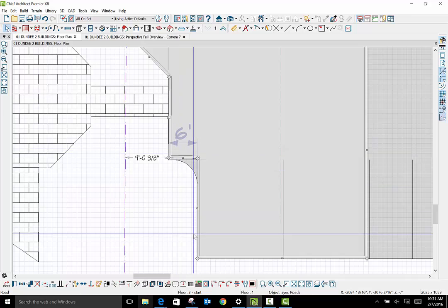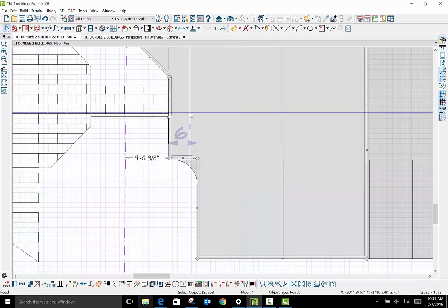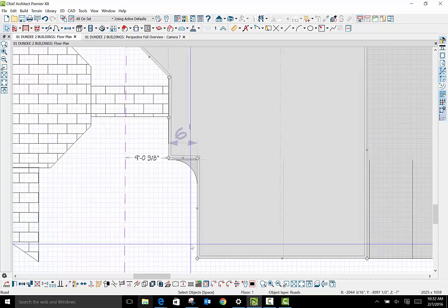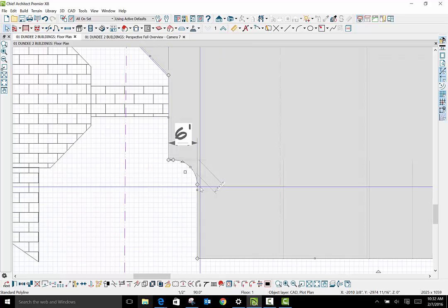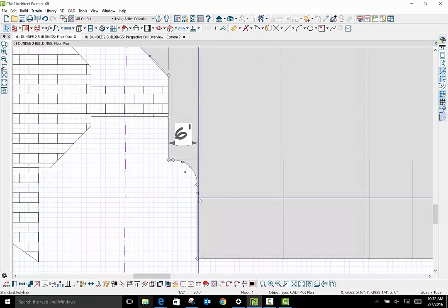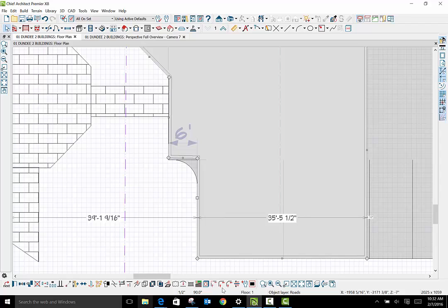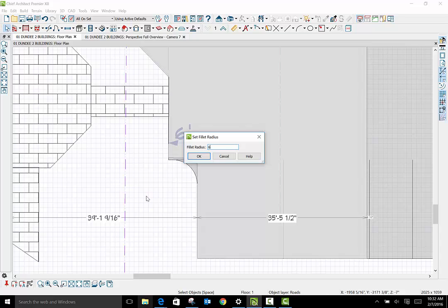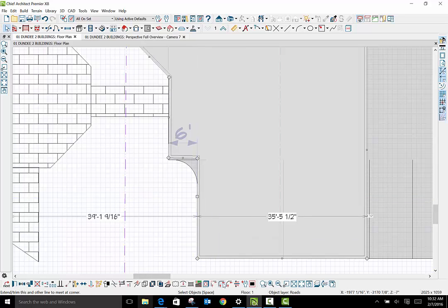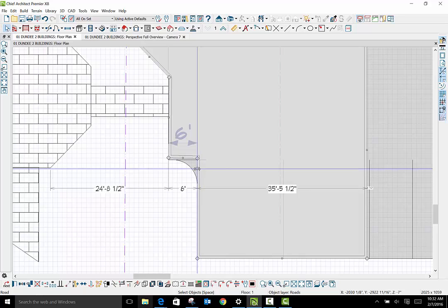And now, this is just as you're backing out of this stall, handicap guy backs out. And you roll over the corner of this, we'll put a little radius in here, a little 5-foot radius. So we'll go here. Tab it. And go to radius, fillet radius size, we're going to go to 60 inches. I'm going to pick this guy. We are going to fillet it in there.